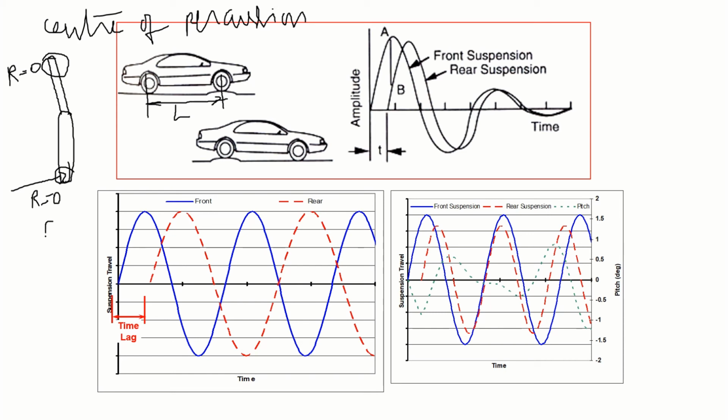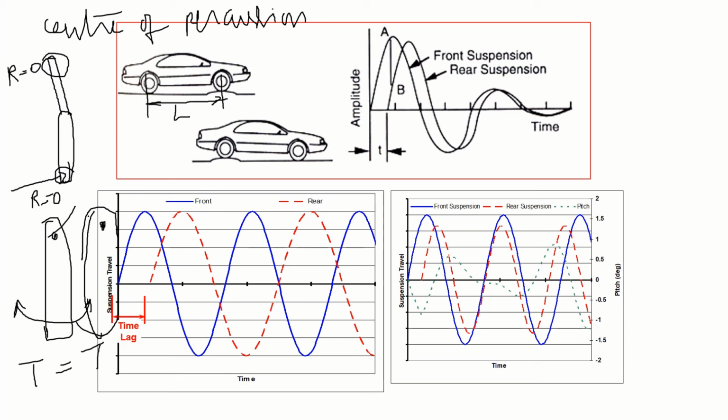That means if I take this as a compound pendulum and hang it at this point, oscillate it and find a time period, and then reverse it, hang it and find the time period again, both will be equal. Then this is called the centers of percussion. So whatever reaction happens at this point should not happen simultaneously at the other point.